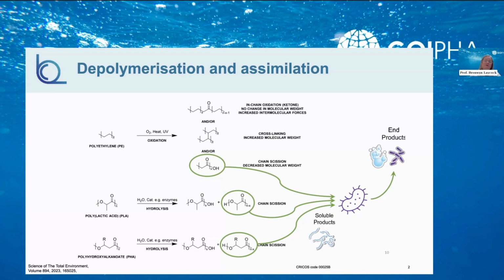And it's also very important to understand, and we'll be talking about this later, that you have biopolymers which are degradable by water when they're catalyzed by enzymes in the natural environment, such as PHA, versus others that need elevated temperatures and primarily biodegrade through abiotic hydrolysis, so non-enzyme driven, in the early stages until the molecular weight gets down low enough, such as polylactic acid.